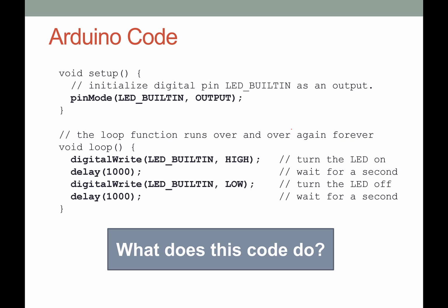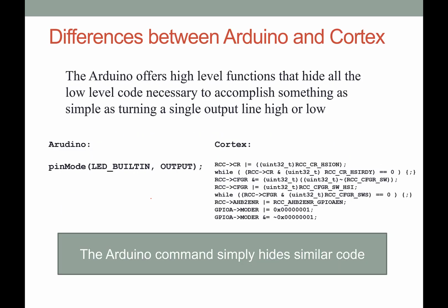Okay, this is the example Arduino code that you would use. You can see that we're putting a digital pin high, waiting some length of time so it turns on and we see it. Then we turn it off and delay more time. If we put that in a loop, we're going to see the light turning on, off, and so forth. So this is just the simple LED turn on and off for Arduino. But let's see how we would accomplish that using our microcontroller in this lab.